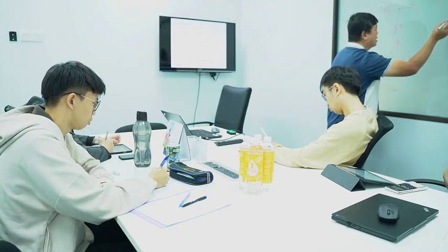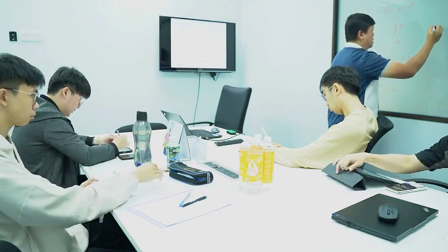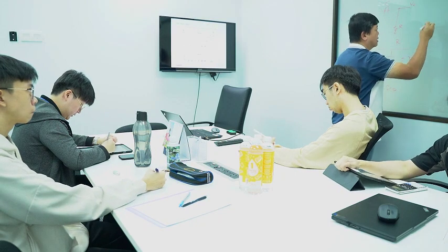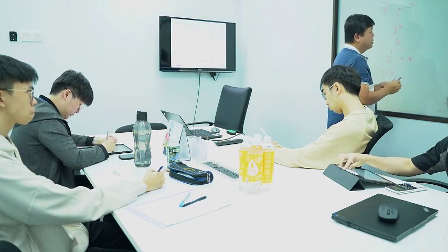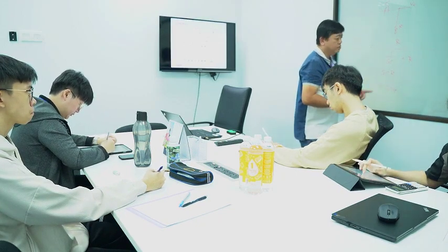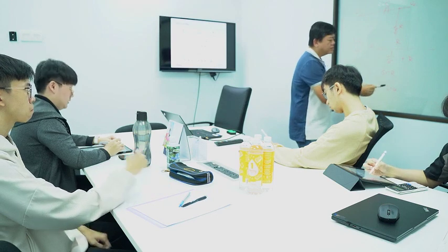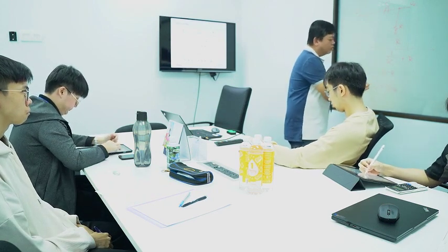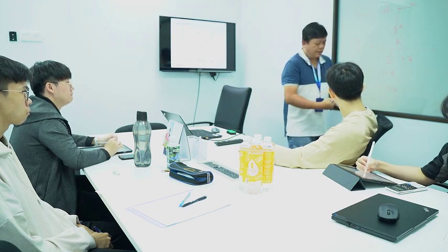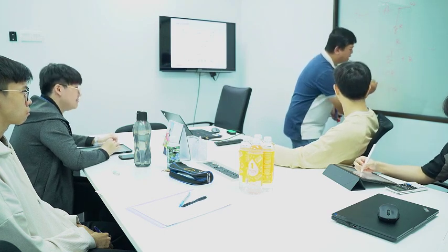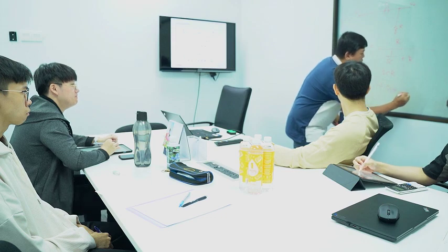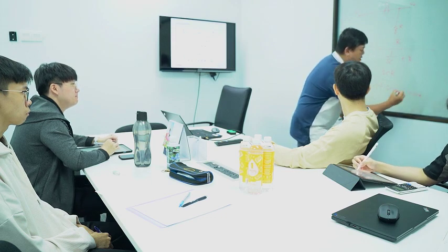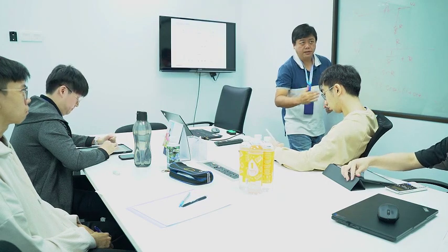So we normally have the origin zero and the origin pole also. When you have these terms, they always come together. Always remember this term: 1 plus sCR, 1 plus sCR, right? Let's say you have more poles, basically you just multiply together, 1 plus sCR, everything multiplied together, because the gain stage you can multiply, right?